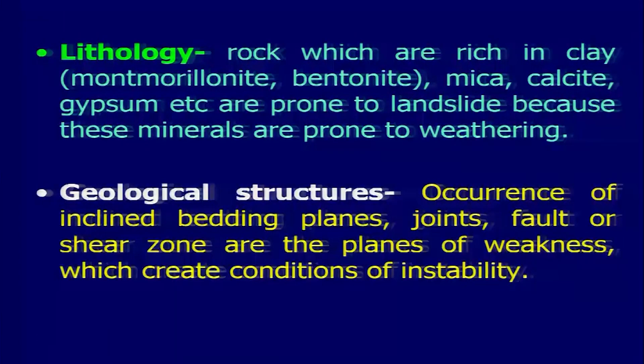And the geological structures, if you are having inclined bedding planes, joints, faults or shear zones, are potential planes of weakness which create conditional instability in the area.